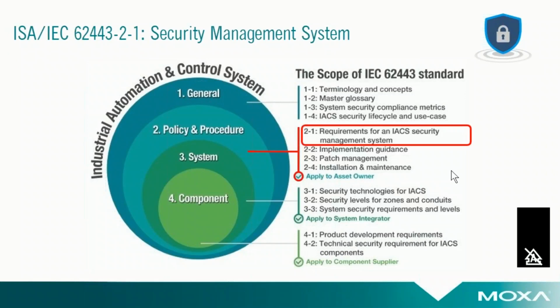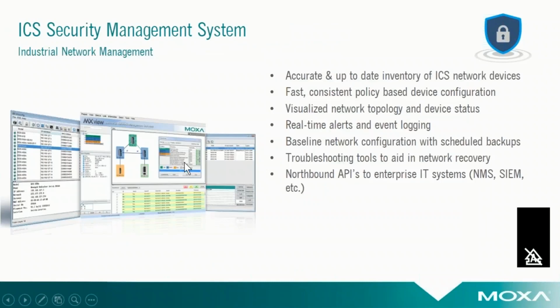So after the fact, they were looking for a way to keep this from happening again, and by simply deploying some industrial firewalls and using deep packet inspection to only allow read access to those production lines, they eliminated the possibility of that happening again.